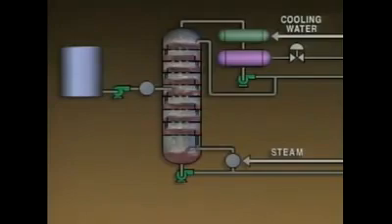For example, if the differential pressure increases, the boil-up rate may be too high. In other words, the reboiler may be returning too much vapor or vapor-liquid mixture to the tower. This problem can be corrected by reducing the boil-up rate.